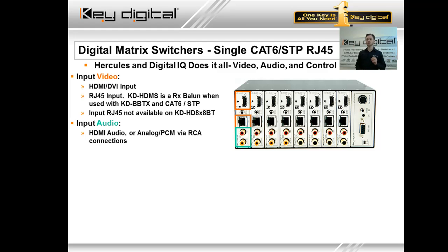That being said, there are some that do support Dolby incoming formats and decode them to 2-channel. Very cool technology built into the television. But say you have one of those TVs that only supports 2-channel audio, what if you're trying to select that video source that's already outputting Dolby audio format? Well, then that display wouldn't be able to give you any audio whatsoever in the case that you were working with another manufacturer's matrix where it only offered you those 8 HDMI ports.